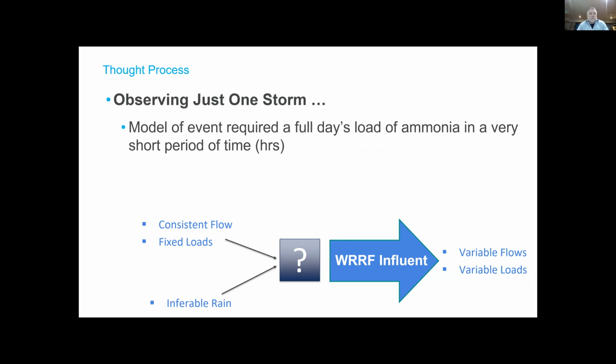So this all came about because I was sitting at the treatment plant one day, and I was watching the SCADA screen, and it was not raining at the treatment plant. Okay, so it was a cloudy day, but it was not raining. And I watched the effluent ammonia at this treatment plant start to rise, and it was in fault within a couple of hours. And I walked downstairs to the operators and I said, "Are you watching this screen?" And they looked at me and said, "Why? What's going on?" I said, "Because your plant is about to fail its consent." And there was absolutely no indication at the treatment plant that something was going wrong out there.